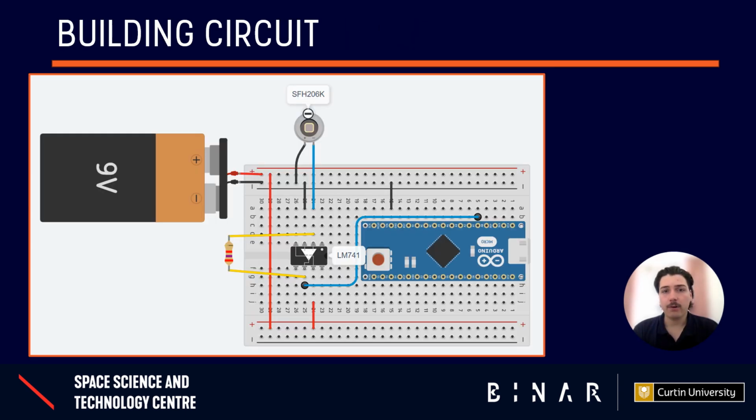Once you have chosen the correct resistor from your kit, it's time to build the circuit as shown. Keep in mind that pin 1 on a chip is usually marked by a notch or small divot. This is important for getting the orientation correct. Also, be sure to connect the battery last to avoid accidentally damaging any of the components.